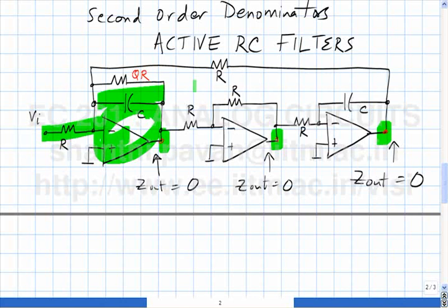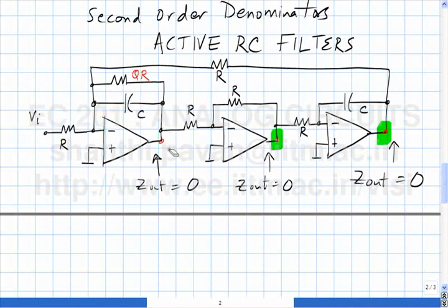Quite straightforward. Okay. So, given a transfer function, you should now be in a position where you will be able to implement any high order transfer function by simply breaking it up into second order sections. You know how to realize a second order section, and you can cascade them all, and you will be able to realize the transfer function that you want.